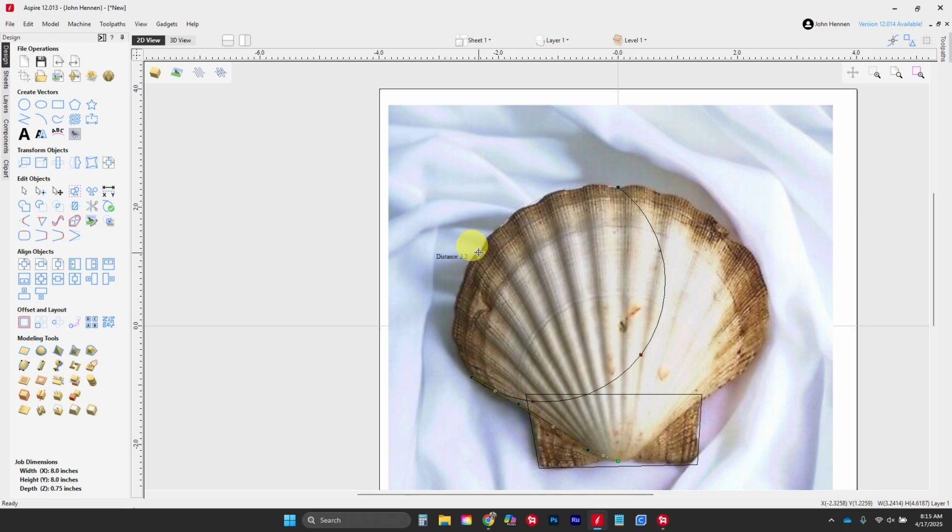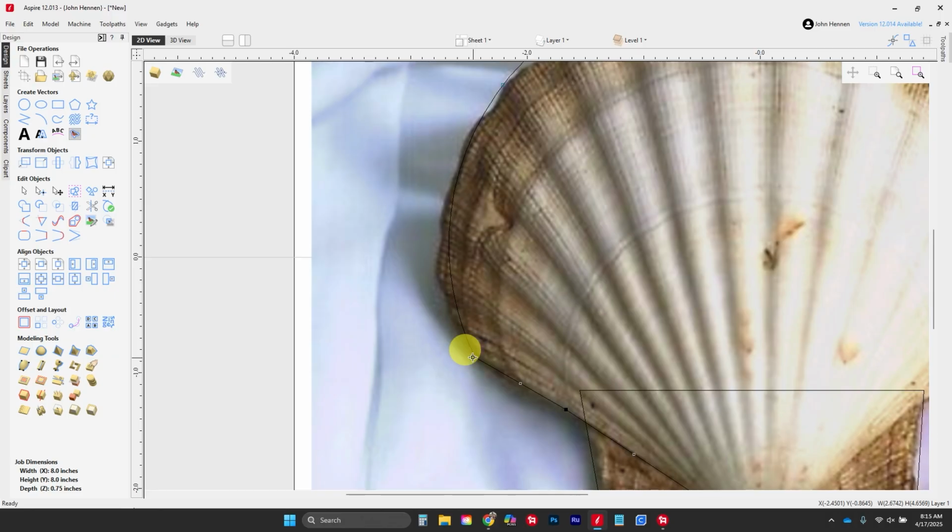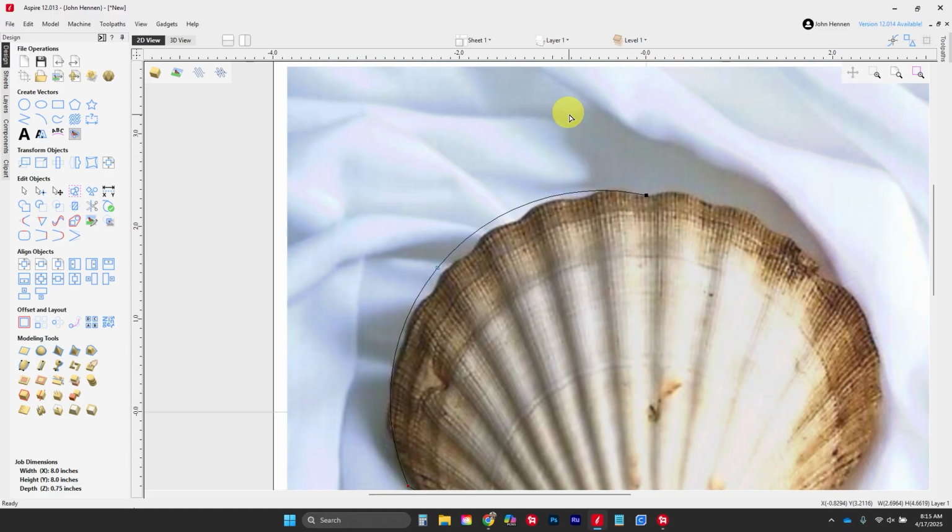Now you're going to notice that there are those little waved pieces, and we're going to make those with a 2-rail sweep. And on this side, I want to bring it out and up more. We'll delete this node as unnecessary, and let's just bring this one up a little. Okay, now you'll notice it's not a perfect arch. We want it to look about there. Then we're going to change that from an arc to a Bezier, and I'm going to pull this one down till it's flat. And I'm going to pull this one in a little bit.